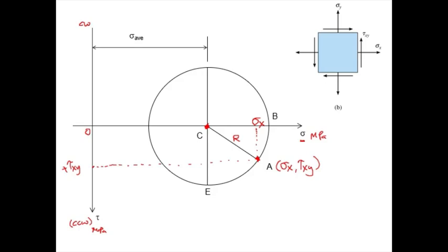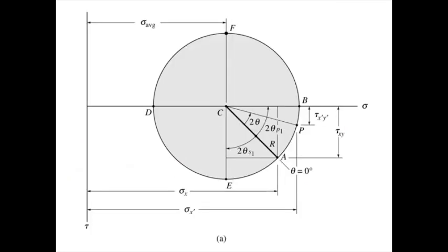And the rest is doing whatever you want to do with the Mohr circle, as I have explained before, what a Mohr circle can do for you. Right. So point A here is your reference, or in other words, this is the x-axis location. All angles in Mohr circle are twice the actual angle. Now point B represents location of principal stress 1 or maximum. Point D is the minimum value. So you have coordinate here is sigma 1 or sigma maximum and 0. Coordinate for point D is sigma 2 or minimum stress and 0.